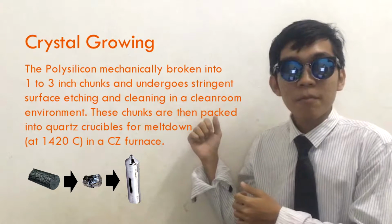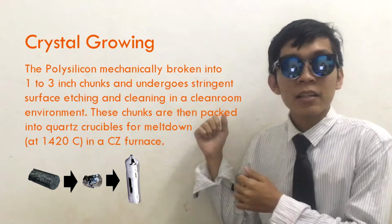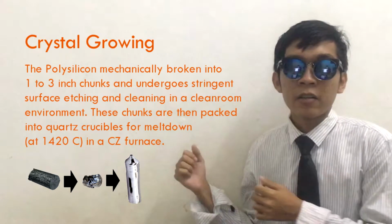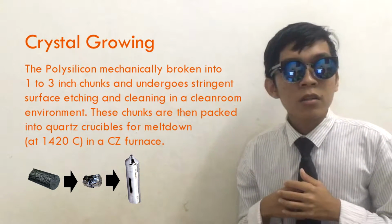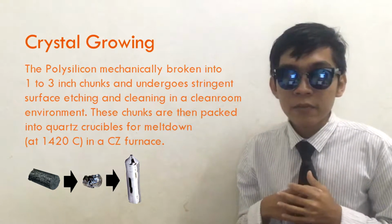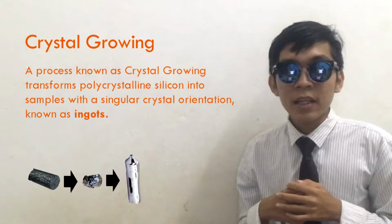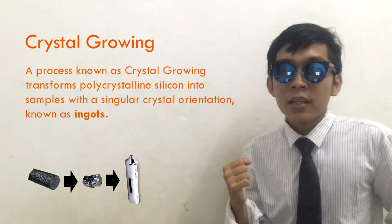The polysilicon is mechanically broken into 1 to 3 inch chunks and undergoes immediate surface etching and cleaning in a clean room environment. These chunks are then packed into a quartz crucible for meltdown at 1420 degrees Celsius in a furnace. A process known as crystal growing transforms polycrystalline silicon into samples with a single crystal orientation, known as ingots.